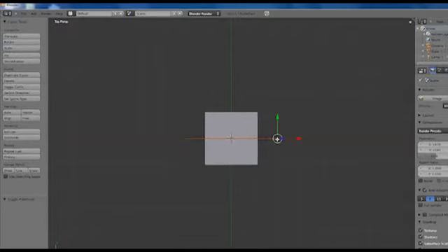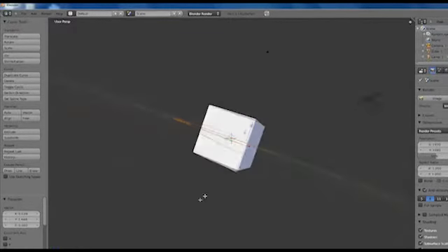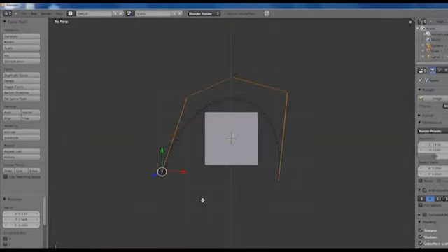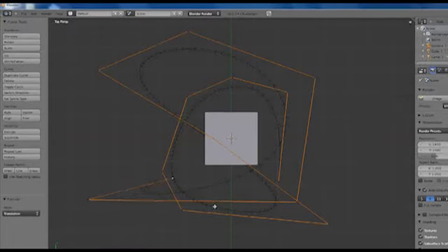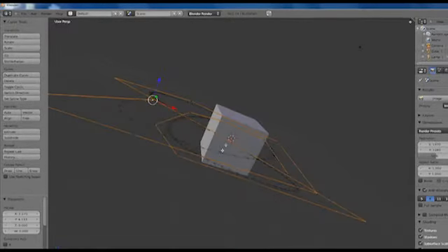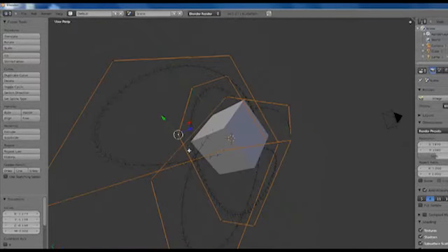We're adding a path here. I'll go into edit mode, tab to edit mode. I'm going to go fairly quickly, so if you're not familiar with the interface, you might want to check back with us later. Anyway, away we go. So I'm pressing E here to extrude the curve. It's all on a flat plane at the moment. We'll just go through a little bit more. Okay, that's interesting enough. It's quite a large curve.